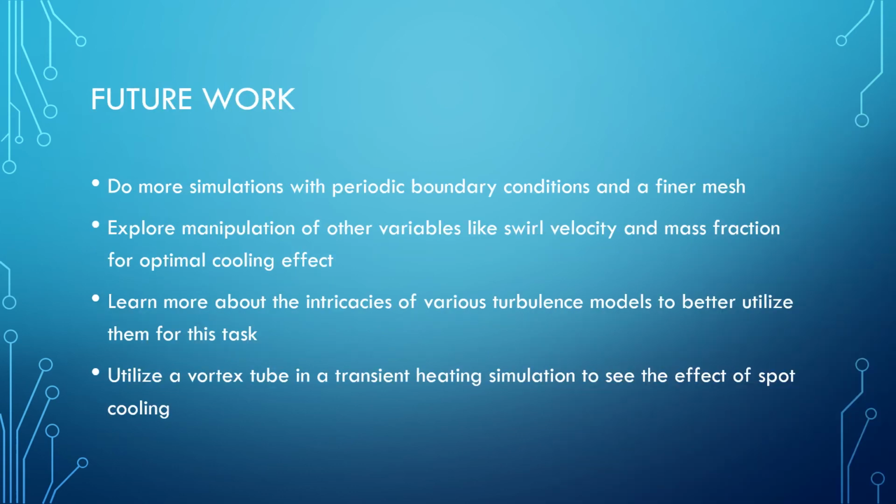And in the future, along those lines, I kind of want to do some more simulations with a periodic boundary and a finer mesh, see if I get consistent results, or if I'm going to get closer to the results that Mahmood and all of them got. I want to see what happens if I manipulate the mass fraction, see what the maximum refrigeration I can get is, see how my swirl velocities compare to theirs.